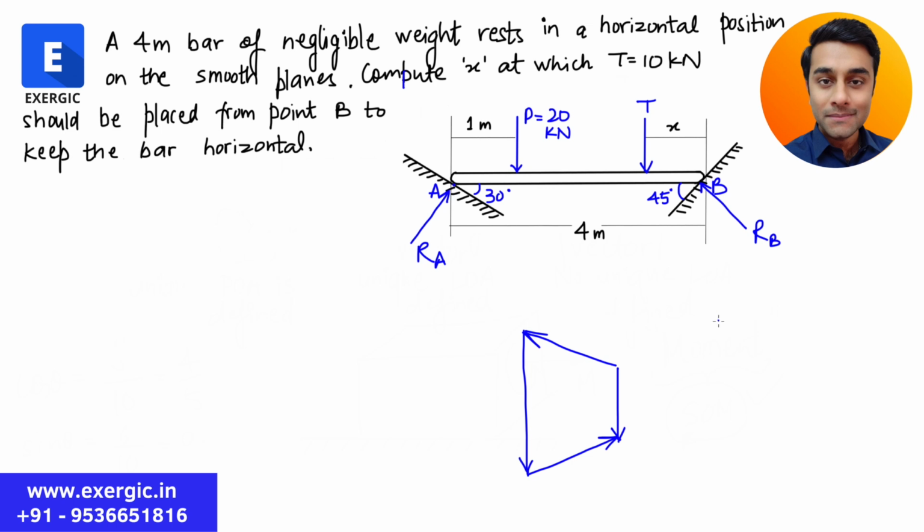You will say that, yes, sir, definitely. We have 4 different sides. It has 4 sides present. It is getting closed, and it is a force polygon. You are incorrect. The direction of the arrows, I also told you which one is to be considered. All those arrows should be cyclic. They should form a cycle.